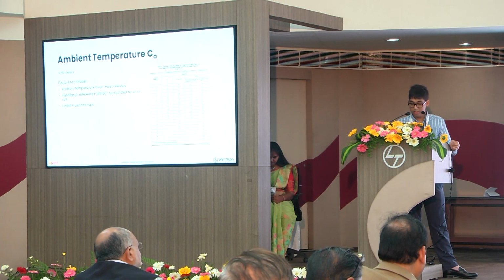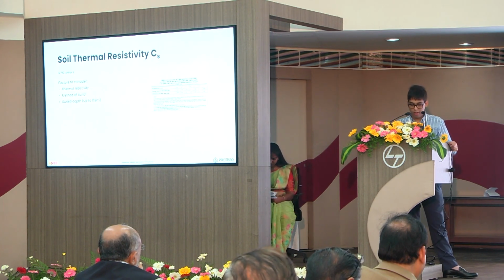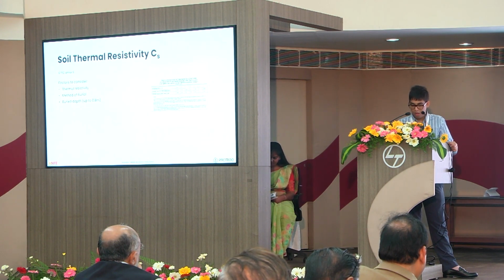Is it in the air? This is a separate table for in air, and a separate table for in the soil. Again, soil thermal resistivity. If the cable is buried in the soil, IS 732 and SP30 only consider thermal resistivities up to 2.5 Kelvin meters per watt.